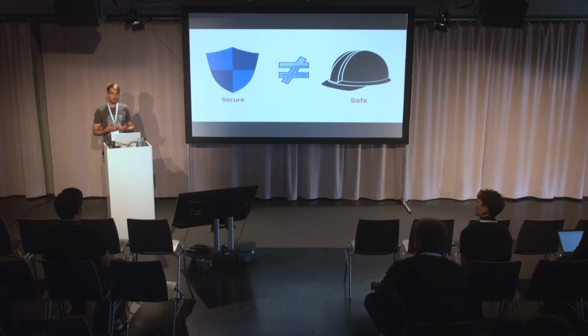One thing I will talk about, fail-safe updates. Fail-safe updates are not secure updates, so we have to differentiate here. So fail-safe means you protect your software against things that you know can happen. Like if you are updating your device, maybe you have a power loss because someone unplugs the device. If it would be a secure update, that means only a signed version of a new firmware will be installable on your device.